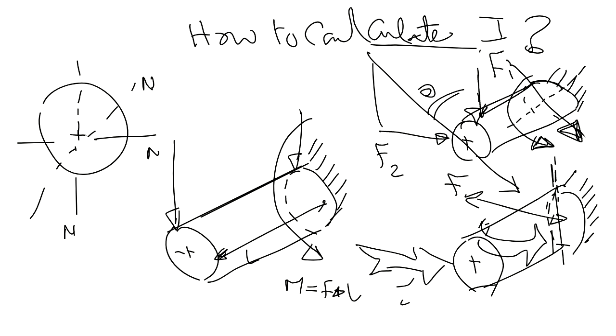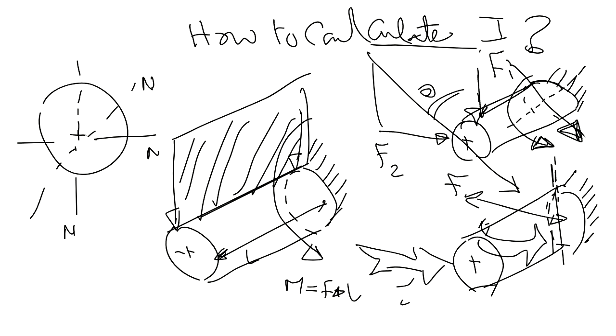So now you agree that my moment will be acting along that vertical plane, guys. You see that vertical plane, because you moved your force along that vertical plane. So now I can claim that the direction of the moment, or the plane of the moment, is the vertical plane. Do you all agree, including Muhammad Taha? Yes. Okay. So now we claim that our neutral axis should always be perpendicular to the plane of the moment.